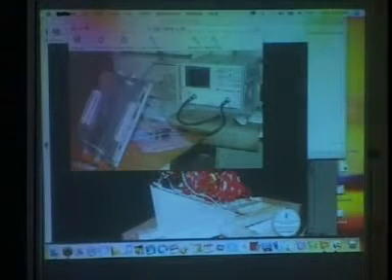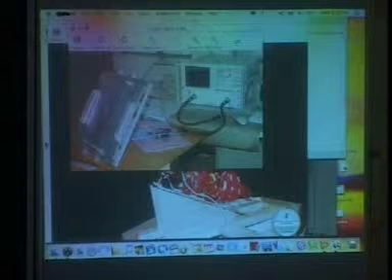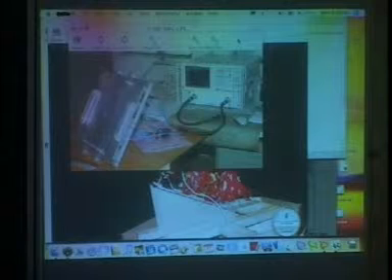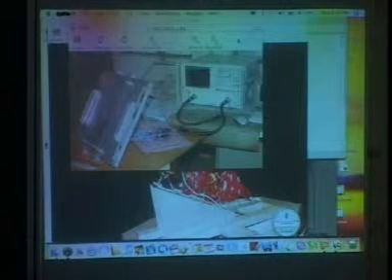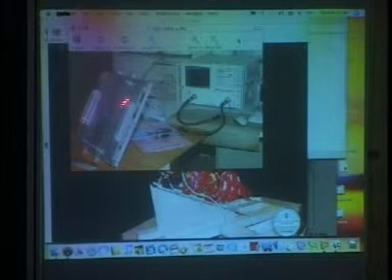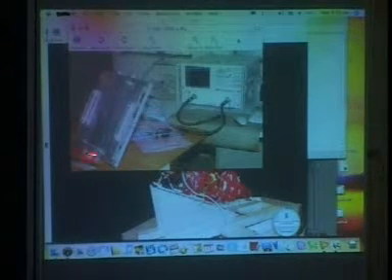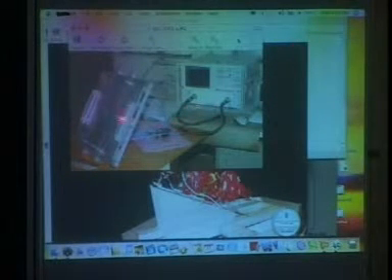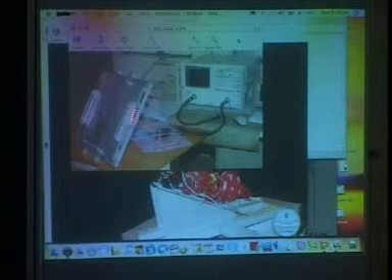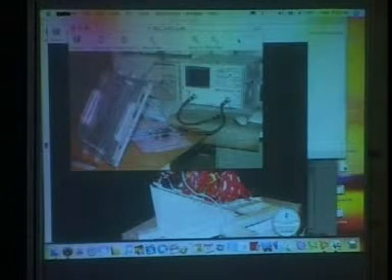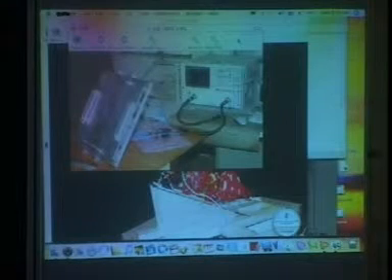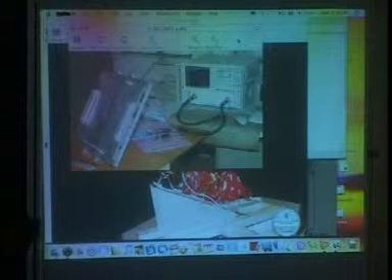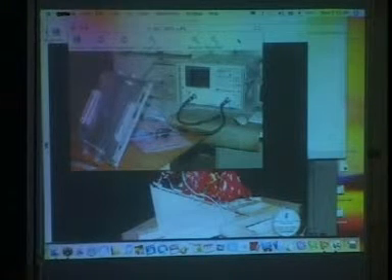See here, in the MIP antenna we used one inverted F antenna because between the Moon Impact Probe and the spacecraft there was some communication required, and that was at UHF. Because it is in UHF, we used an inverted F antenna. So that inverted F antenna is being tested here for impedance and other measurements. But this is a very important element which has come up recently. We have seen a lot of publications from various people, and it has found an application in our spacecraft also. Because it is in UHF, we found it was one of the best. So with this, we have completely used it.